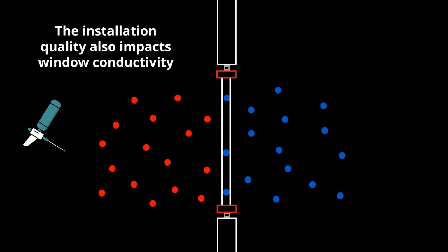The quality of the installation also makes a huge difference. Most windows are retrofit, meaning there's an existing frame that stays in place when the new windows are installed, and then there are vinyl or trim materials put around these openings to create the finished aesthetic. Because that existing frame is typically left in place, mostly because it's very, very expensive to rip out the existing drywall and stucco around these frames, you're going to want to make sure that when somebody goes ahead and foams those frames, they do a complete job.